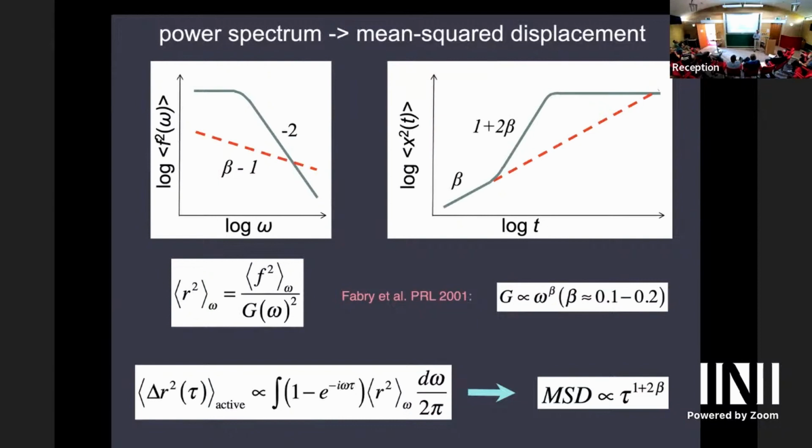Okay. These processes with force, with the time correlation, are then coupled to an overdamped elastic medium or something more complicated. It's basically elastic, so the damping is almost negligible. And in the plateau, you typically have the G double prime dipping down. So the viscosity is much smaller. The G double prime is much smaller than the G prime in that regime. So it's just a rubber ball excited by all these little force dipoles inserted in it. And at that scale, the inertia is irrelevant. It's all low Reynolds number. Absolutely, yeah. So inertia is totally irrelevant. You can think about it as a step. If you take a step in force and Fourier transform that, you get 1 over omega. If you take the square of that, you get 1 over omega squared. It's as simple as that.